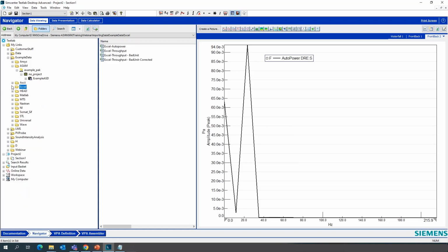One of the advantages, I should say, is how it will handle the unit. And that is one of the reasons why several simulation engineers like to use TestLab, because when somebody asks them to plot some data, they may be showing it in millimeter per second square, but if they ask, hey, can you show me that same information in meter per second square or feet per second square, for example, the conversion can be done very easily in TestLab in the display itself without having to rerun the whole simulation. That is one unique advantage of TestLab.